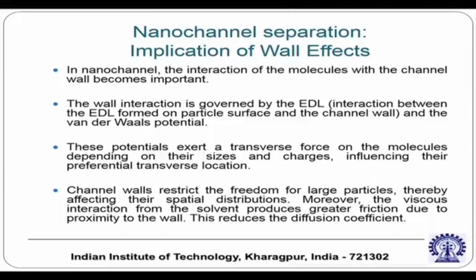Not only that, interaction of molecules with the channel wall will become important in nanochannel based separation. So the interaction is basically the van der Waals interaction and the electrical double layer interaction between the EDL of the particle and the EDL of the wall. Now all these interaction forces are important in the nano domain.